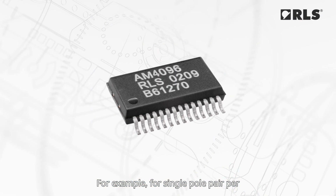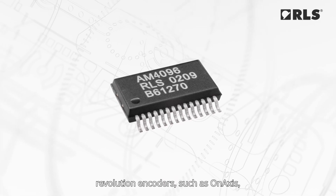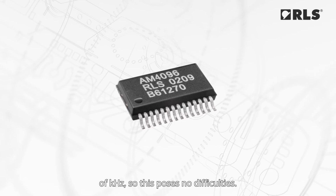For magnetic encoders, linear or circular Hall arrays are usually employed that can use tens of sensor elements. The Hall element power consumption is therefore significant, and various techniques need to be used to reduce it, such as reducing their duty cycle depending on the sensing requirements. For example, for single pole pair per rotation encoders, such as on-axis, the input frequencies are slow, in the range of kHz, so this poses no difficulties.